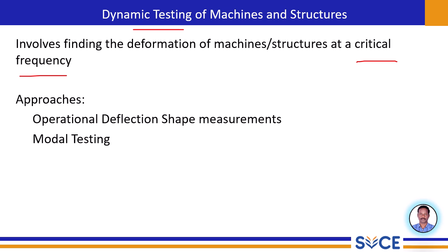The next one is modal testing. This sounds very familiar to us, that is, it is closely related to our main topic, modal analysis. In fact, modal testing is the practical application of modal analysis. It involves deliberately exciting a structure with a known input force and measuring its vibration response at various points. The goal here is to identify the structure's inherent dynamic properties. Let us see in detail from the next slide onwards.